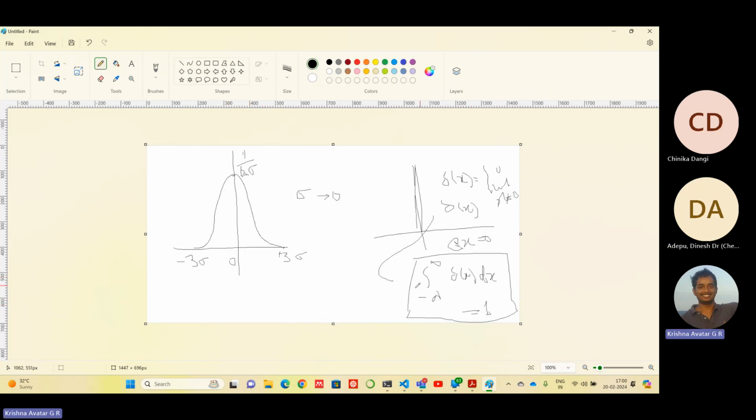That's very right. So what we are doing here is, when we are trying to apply that point load at the tip of the bar, we are using the substitution property of delta, which means we are integrating from 0 to L, P, which is our terminal load, into delta of x minus L, dx. So you convert this into a Gaussian. Yes, we are modeling it as a Gaussian.